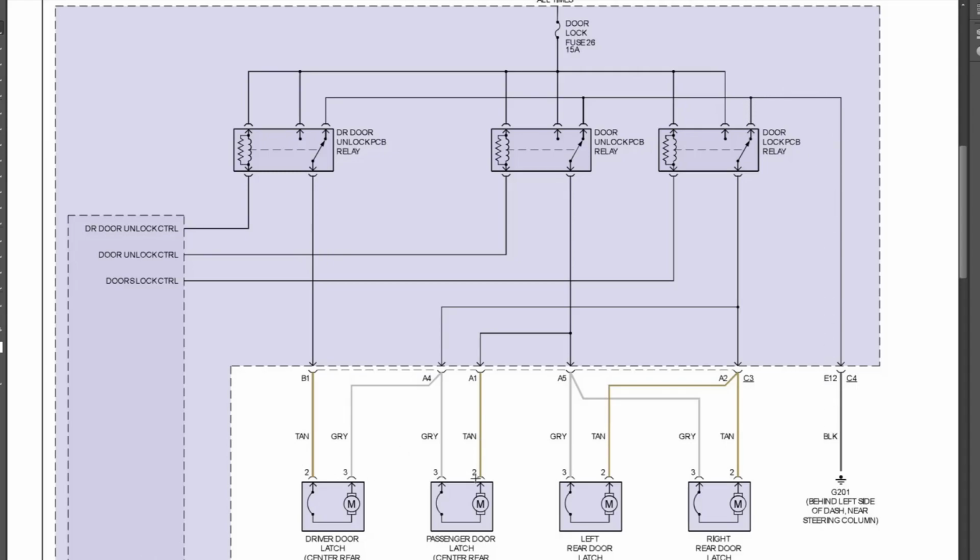Let's grab the other one. Pin 2 up to A1 here. Connects to this other line coming in from another door lock. It goes up to the unlock relay this time through the normally closed set of contacts over, and it's sharing that same ground again. And you'll notice that's the same for all 3 of these door lock motors. So again, you can test this the exact same way, and I'll take you way back even further, and we'll take a look at a